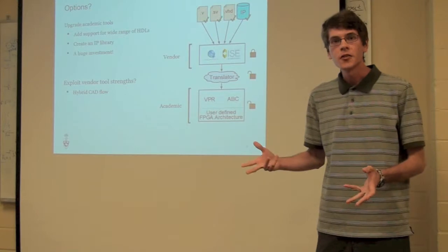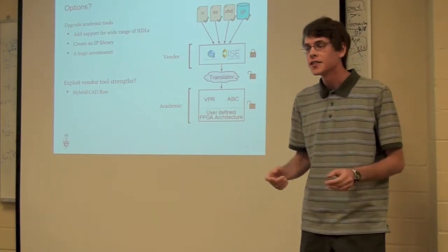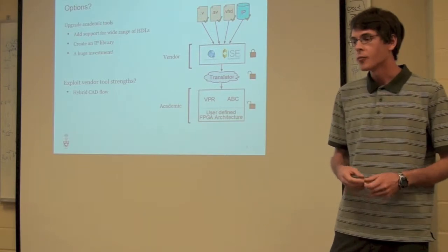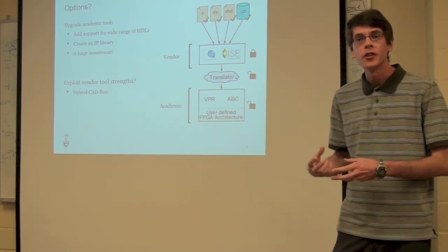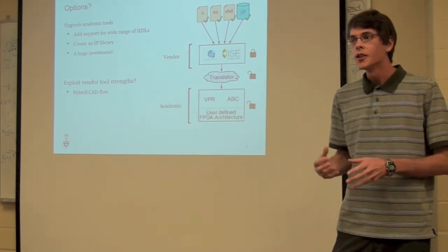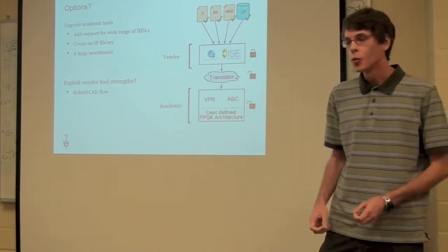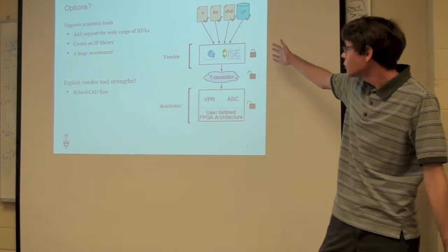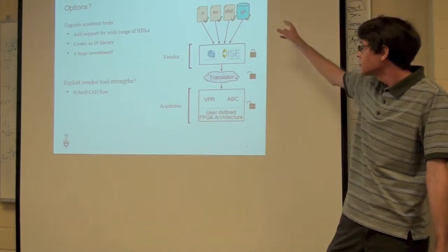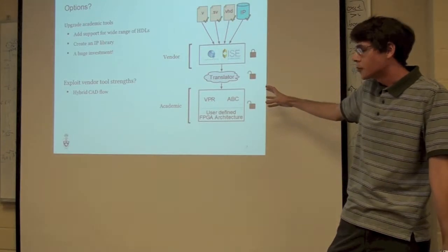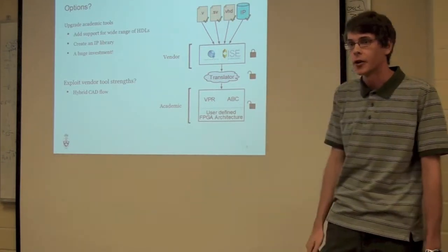So what we thought at this point was basically, it would be really nice if we could somehow exploit the strength of the vendor tools, but still have the flexibility of the academic tools. And so this is where we came up with the idea of developing a hybrid CAD flow, where we use a commercial vendor tool to handle the interface to HDL, and then pull the design out of the vendor tool and put it into an academic CAD environment.